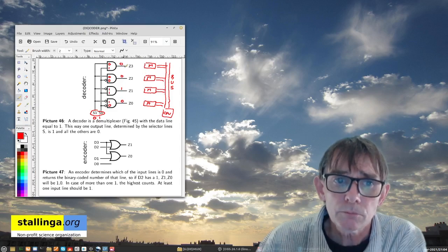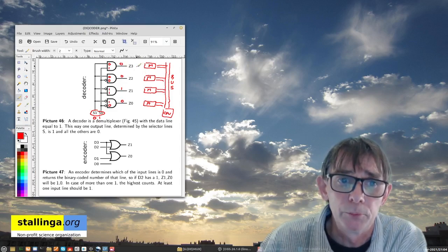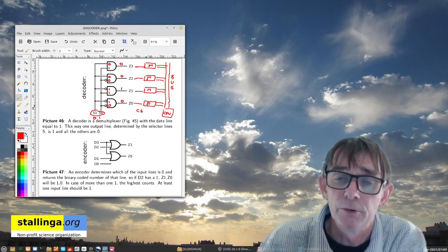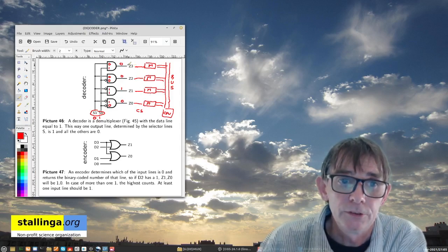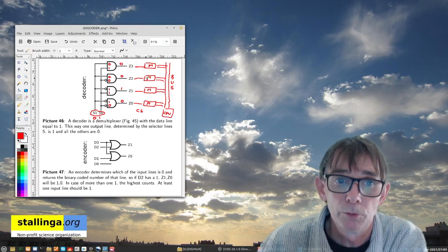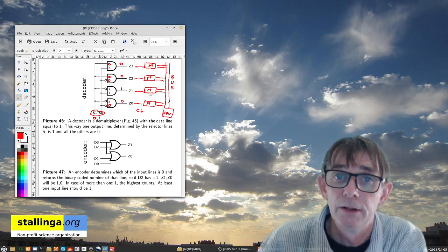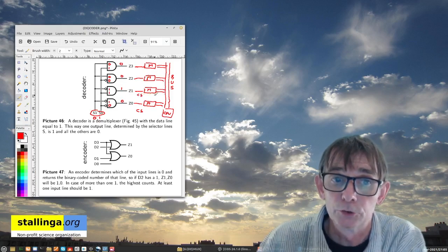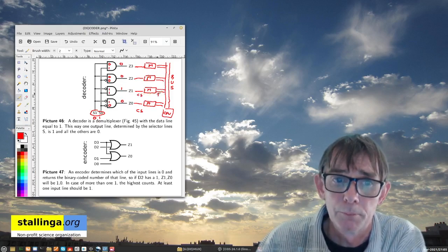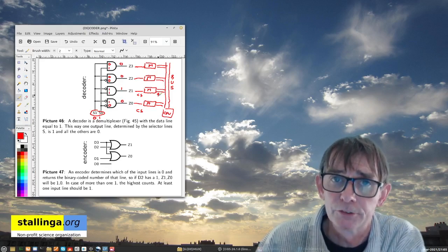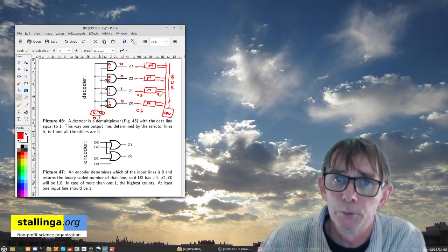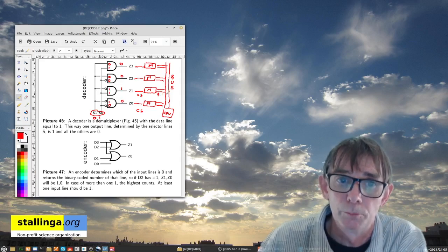So how do I do this? Well, this line I can connect to what is called chip select, or CS. That means it will activate that chip. And in this case, as you see, this one will be deactivated, this one will be deactivated, and this one will be activated. And for instance, this chip select is also used to put the output in tri-state. Remember the tri-state from CMOS technology, how to put things in a high-ohmic state, so that it will not communicate with the bus and it will not cause a short circuit.